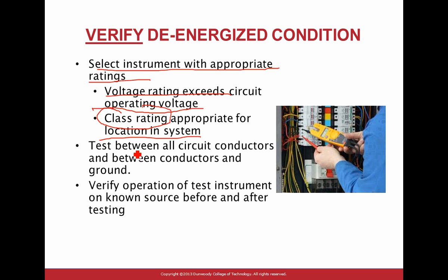And test between all circuit conductors and between conductor and the ground. When you verify, guys, phase to phase, phase to phase, phase to phase, phase to ground, to ground, to ground. That's it, done with a 3-phase system. And then verify operation of the test instrument. And then before and after, you verify the voltage.